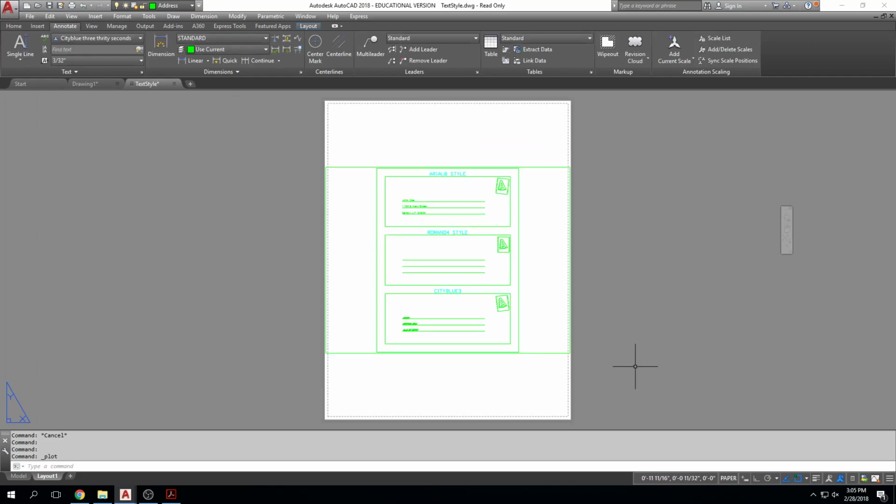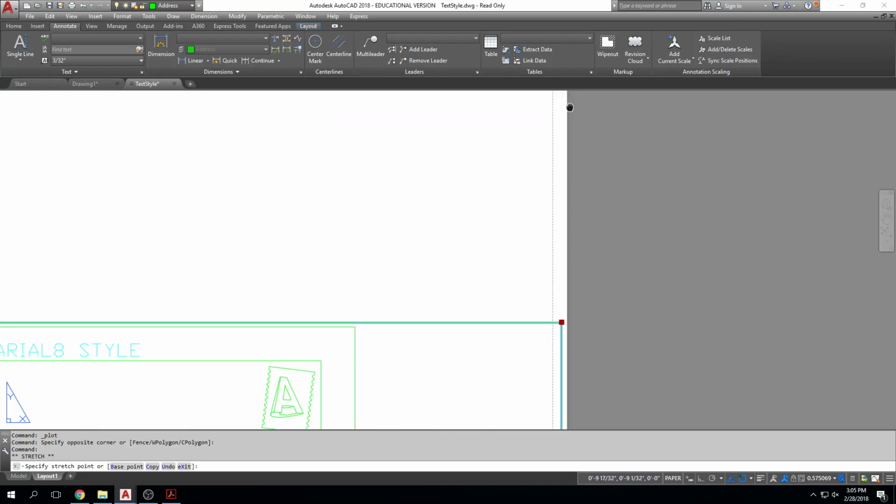Okay, now if I cancel out of there, I've just set my page up so it will print an 8.5 by 11. Okay, this is my viewport. Oh, because your page layout is controlling that. You made a page layout. Yeah. So now hit cancel. So right there, set current. So that's your page setup for that.